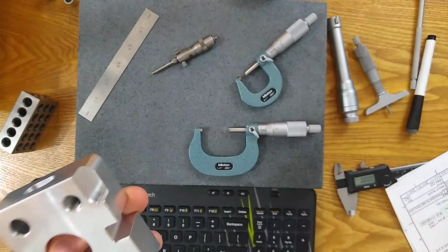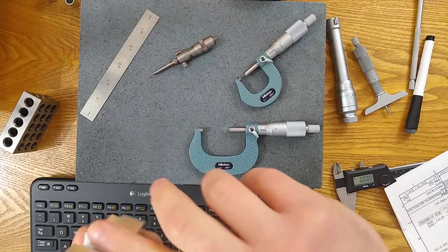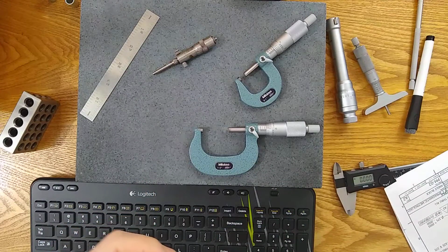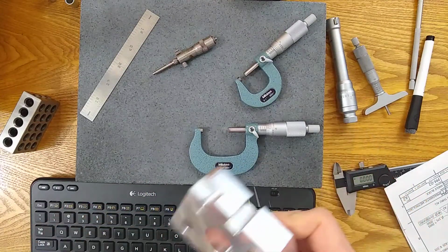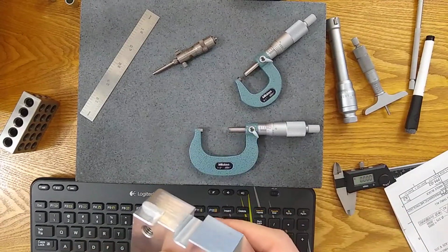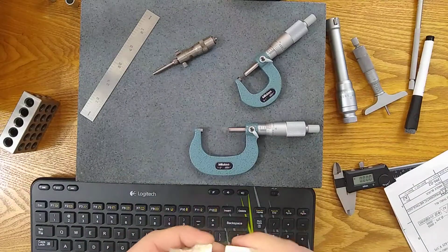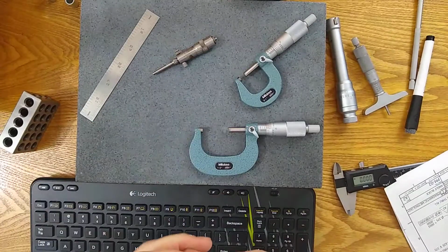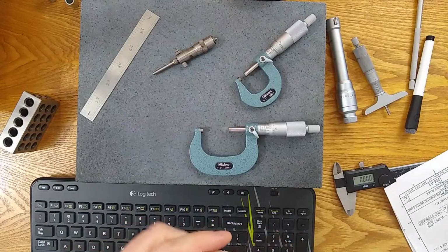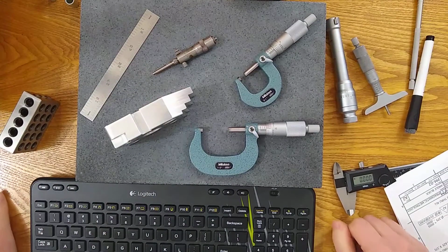Were there any obstacles or pitfalls that you didn't avoid that affected your result? You'd look at it and think, oh, this doesn't make sense, I must have missed something. Oh yeah, there's a chip inside or some extra material that you didn't notice when you were looking at it, but it's still in there. I can't tell you the number of times I've measured a blind hole and my micrometer or my pin stops. I'm like, why is it stopping? Then I look inside, and there's a giant chip ball in it, and it's only 1 out of the 10 holes that was drilled, but I just happened to pick that hole first. So stuff like that can always mess up your inspection.